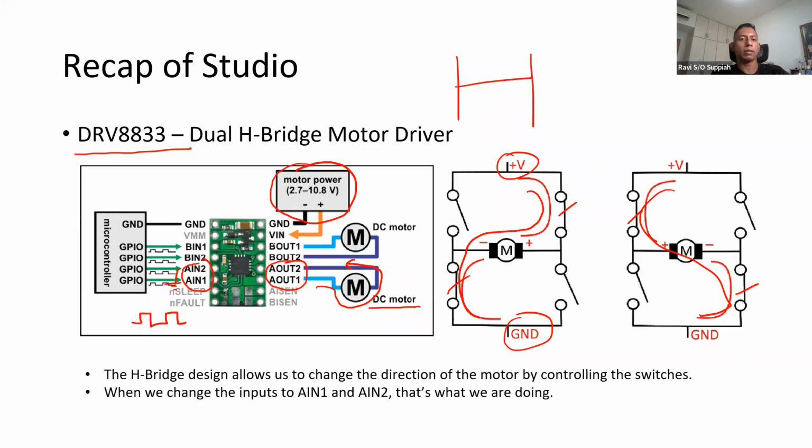So this motor driver chip, you can think of it as simply an amplifier. Whatever signal comes here is of course 0 volt and 5 volt, but at the output side it is amplified because of the higher voltage that I'm able to provide here, to drive the motor. So that is how the H bridge works. You use that in the PWM studio. We didn't go too much into it, but it's good to know, so that when you look at it again later on when you're building the robot, you know how to do the connection.